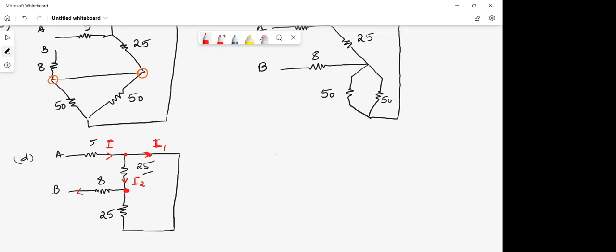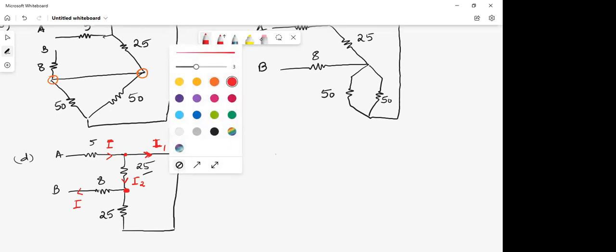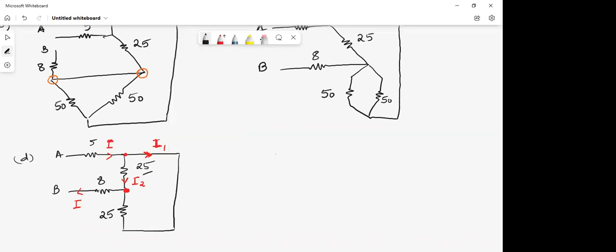I only. Because if I is equal to I1 plus I2, then obviously I1 plus I2 has to be equal to I. And therefore you can see current is coming in, it is divided after passing through the components, and it gets reunited again to give you the same value of current as before division. And therefore this 25 and this 25 are in parallel. Understood? If a step is given to you like this, you must be in a position to understand, yes, it is in parallel. So now we can easily go for the answer. Let me have one more step added over here.